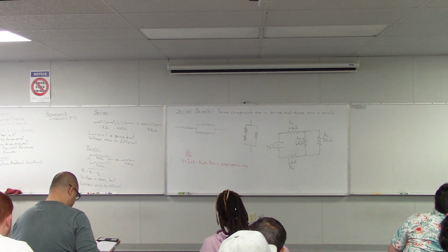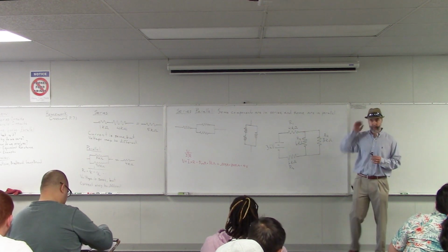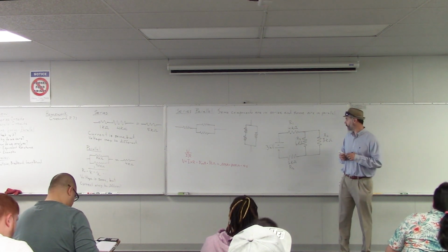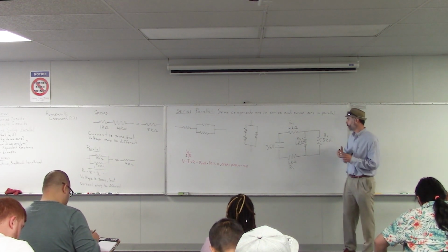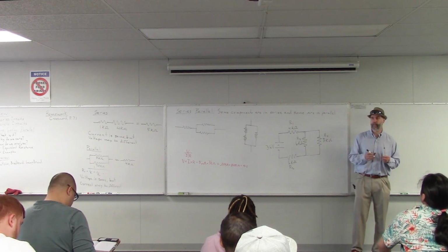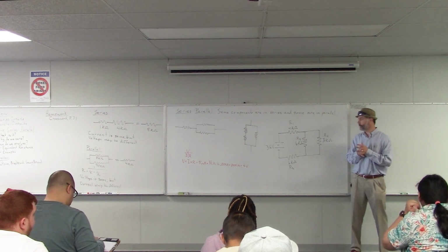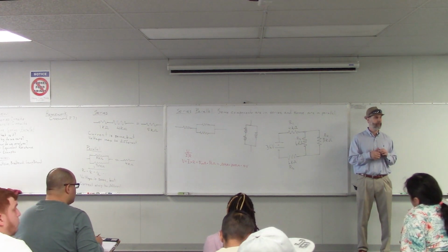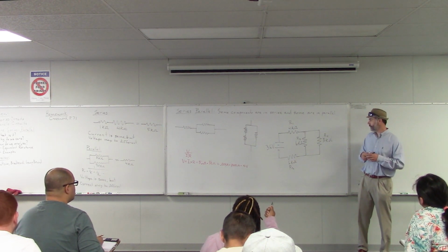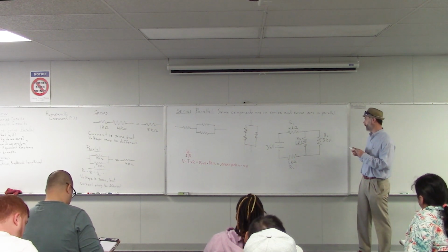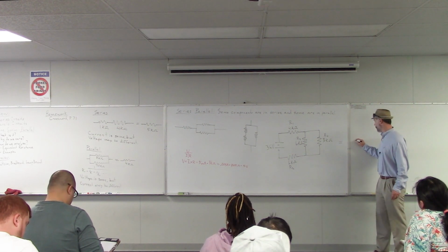Okay, just like before, the first thing we want to do is find the equivalent resistance for this circuit. Remember, we look for any resistors that are in series or in parallel. Do you see any resistors that are in series or in parallel? Yeah, Stephanie. R3 and R4 are parallel, so you can find the equivalent of that and simplify it. Exactly. That's a perfect place to start.